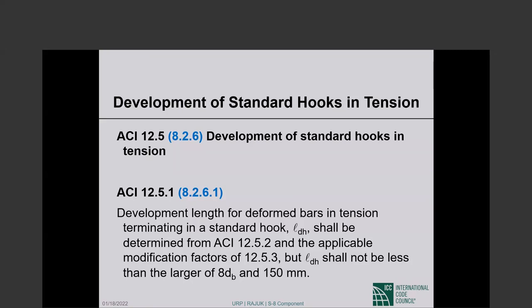So, excuse me. L sub D is the required development length of deformed bar in tension. L sub DC required development length of deformed bar in compression. L sub DH required development of hooked bar in tension. And there will be after this L sub DT, that is something relatively new. That is the required development length of headed bar in tension. Okay, hooked bar and then headed bar.